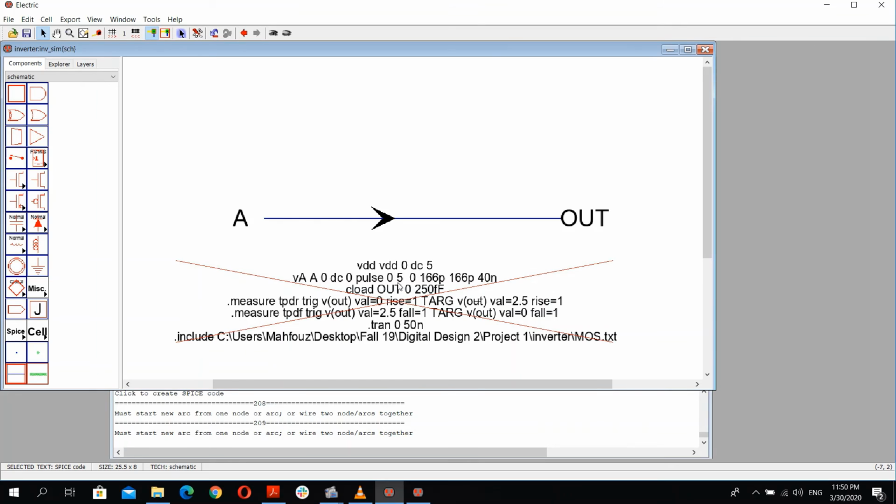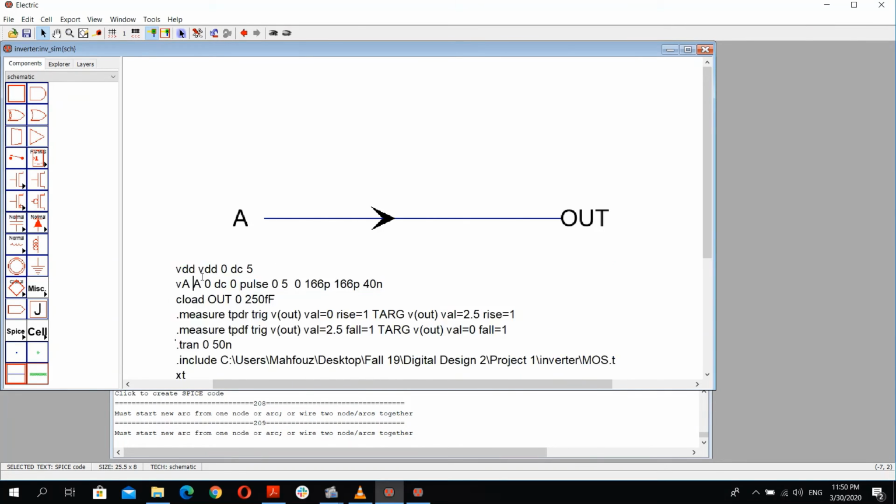What does this Spice code do? Basically, let's open this. We are defining a VDD, defining its values between 0 and 5. And the syntax itself, you can consult in the Spice files on how to write Spice code that the doctor sent you. So we have VDD from 0 to 5.